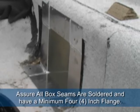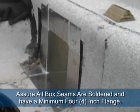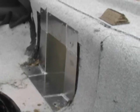Assure all box seams are soldered and have a minimum 4-inch flange. Make sure all corners are closed and soldered. Fasten flange of scupper box every 3 inches on center staggered. Prime scupper at a rate of 100 square feet per gallon and allow to dry.